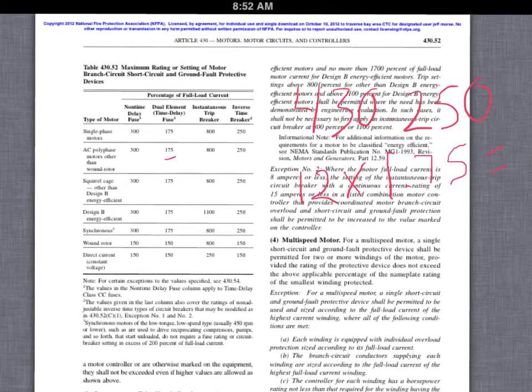Once we calculate that, we're going to get a value of 21. So our fuse has to match that 21 value. So that's our fuse size. However, you guys hopefully remember, we don't have fuses in oddball sizes such as that. So what we're going to have to do is round that up. So we're probably going to be looking at a fuse of 25 amps is going to be the fuse that we're going to shoot for.